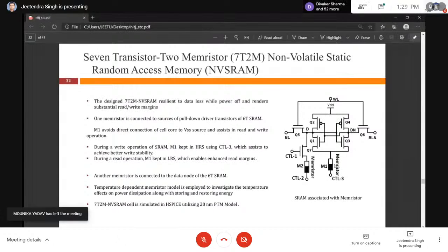It is added to increase the static noise margin, that is the read noise margin and write noise margin, because the noise margin is an important property of the memory, which defines the amount of noise that can be tolerated at the input side so that the output will not be defected.